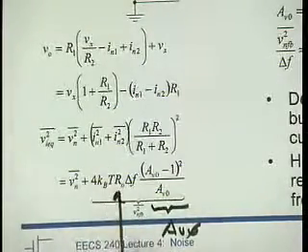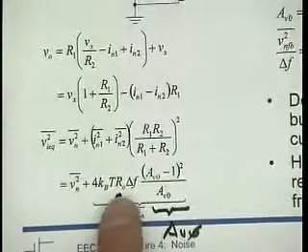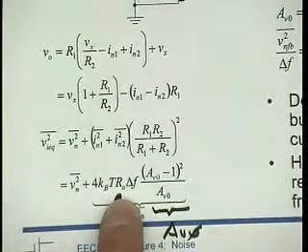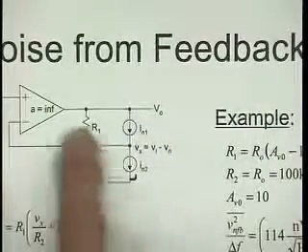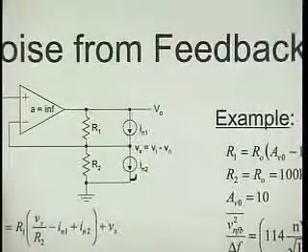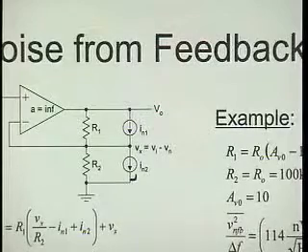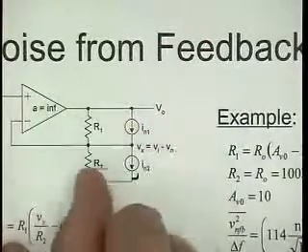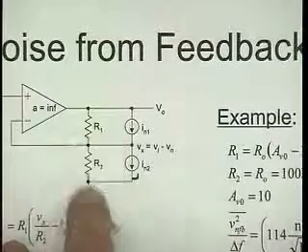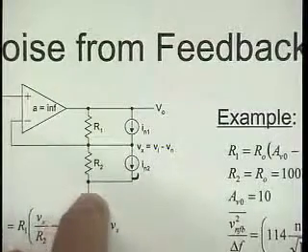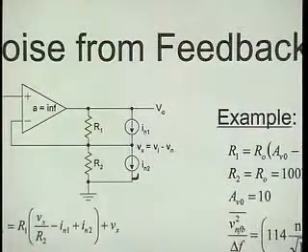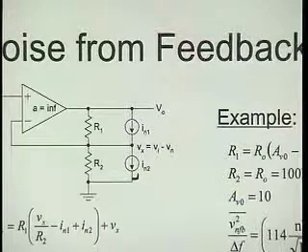Now, if you look at this equation, AV is given by the application. So if I want to make this small, I have to make R0 small enough. R0 is just the proportionality factor for R1 and R2. So of course I can always make R0 small, but the smaller I make it, the more current from my amplifier now flows into my feedback network. Very common problem. You're going to see that all the time.